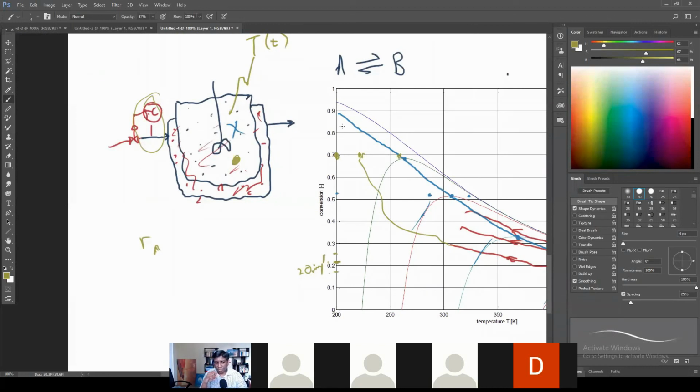In the code that you see, I'm just switching the temperature in the jacket, which is cheating, and I won't say a little bit, it's cheating quite a lot, right? We are assuming we can instantaneously change the temperature in the jacket, whereas actually we should be changing what stream we are using here. It might in fact be that we have two different streams available.